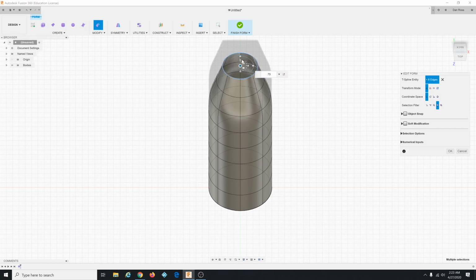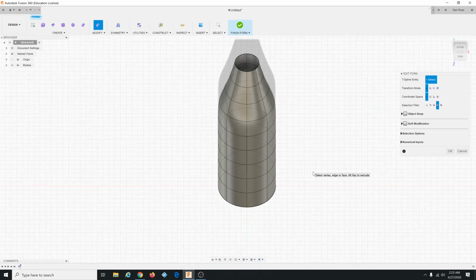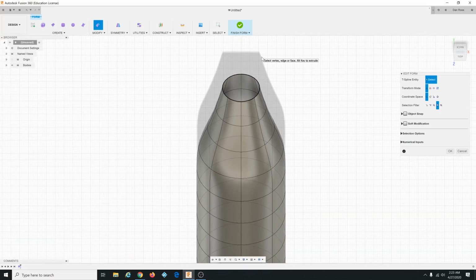Okay, then once again mouse over the arrow, then hold down Alt, drag up 15 millimeters, you get a new edge, let go of everything, mouse over the scalar, Control 0.75. Okay, then click just somewhere on the canvas to be done with that. All right, now we keep going.